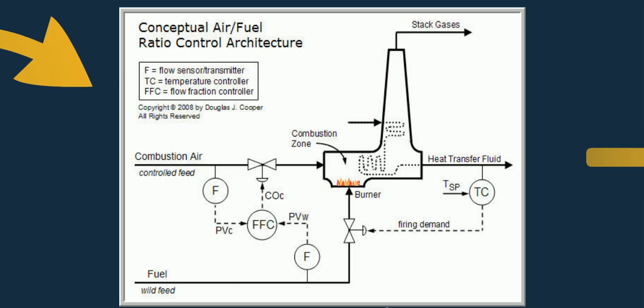On the other hand, if there is too much air present, the heat created from the combustion will simply be used to heat the excess air rather than the chemicals within the process. This is economically unfavorable because you are wasting valuable energy.